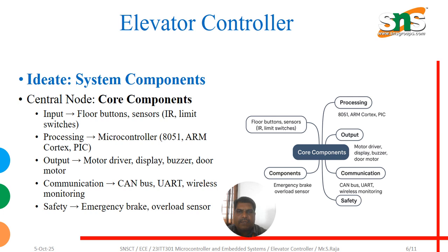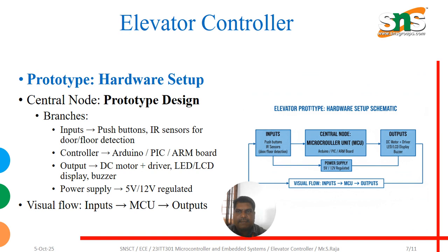So the inputs are the floor buttons and sensors, then the processing is the microcontroller, 8051 or ARM Cortex or PIC microcontroller. Then the outputs are the motor driver, display devices, buzzer or door motors. Then the communication may be defined using UART or CAN bus or wireless monitoring devices. Finally, safety is provided by using an emergency brake or overload sensors.